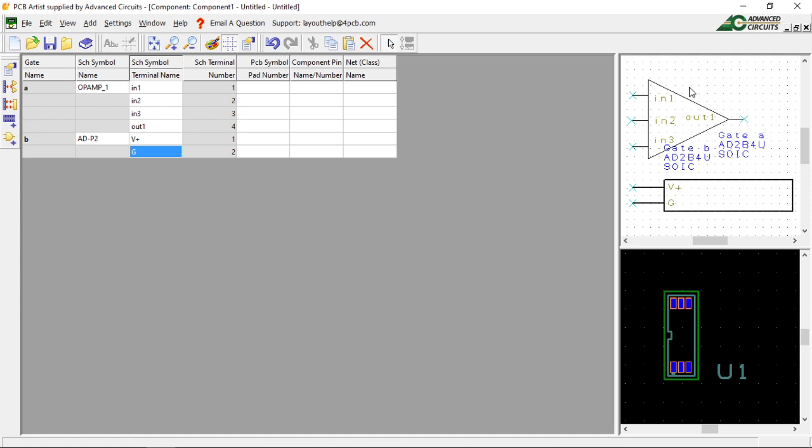And here again, like I say, we could go in and just have some terminals here, and that would have looked much more sophisticated than this. But hey, it doesn't really matter. At least we get some practice doing gates. All right, now, the way I like to do it, there's several ways we can do it. We can basically go in and do assign pins 1 to 1, which will just go 1 1. We can basically go in and do assign pins, and this is the way I like it. So let's do it this way: assign pins. And what you do when you do assign pins is you click something here, and then you click the corresponding pin down here.